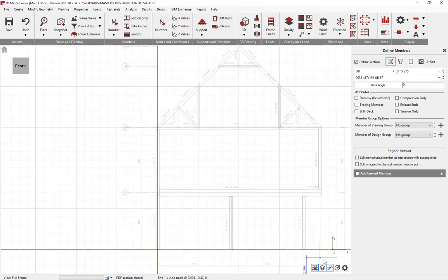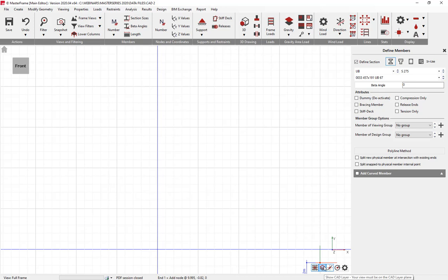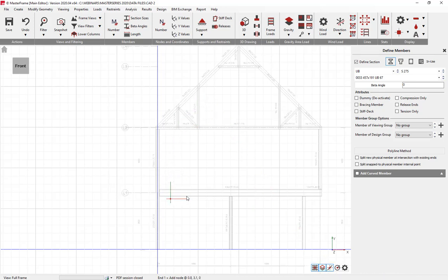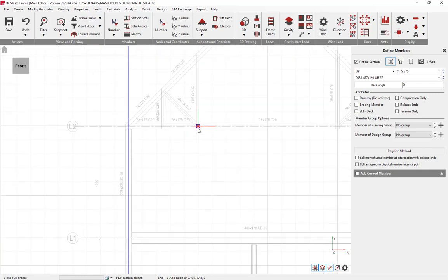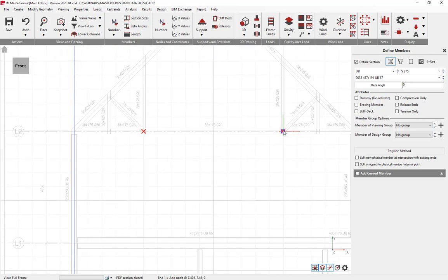And straight away I can see that I have the CAD layer option to turn off and on here. And I can snap on these entities, and snap on their midpoints and third points. I can also hover over to get tracking points and see the tracking lines. In fact, the two tracking points there should provide an intersectable tracking snap point for me. So they behave in the same way in terms of their snappability as to MasterSeries structure.